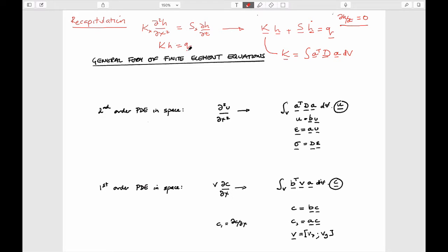And we looked at how to define that and solve it in 2 ways. The first time we met, or the second time we met, we solved it just by writing Darcy's law, in which case we could get the essence of this K matrix. Last time we derived it in a slightly different way in terms of some subcomponents. If you remember, those subcomponents are written below, but the constitutive matrix D is something that links fluxes to gradients of head, gradients in space.